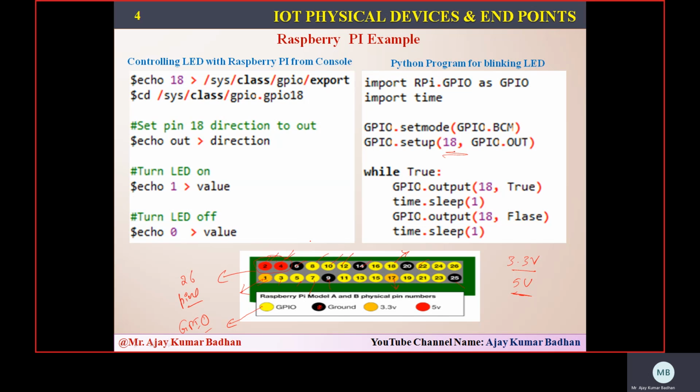So with this, I think you can have an idea. Keep this in your mind so that you can determine which pins you can use for general purpose input output. If you want, you can use 15 as an output pin. So instead of 18, you can write 15. No big deal. You can even write 24 or 22. That's your choice, whichever you want to use.